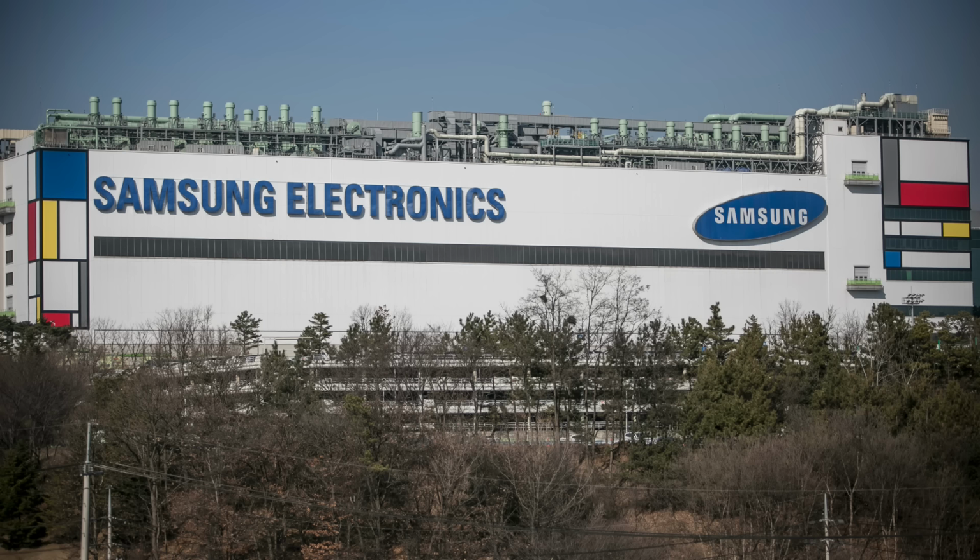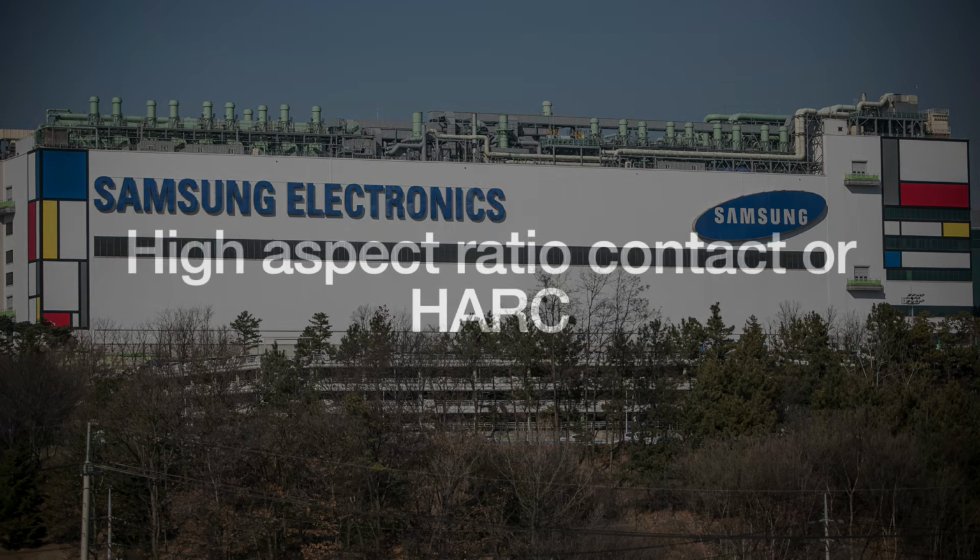But more layers bring more challenges, particularly with high aspect ratio contact, or HARC. Aspect ratio refers to the shaft's height to its width. We want to keep that high. A 128-layer NAND might have a shaft 100 nanometers wide and 6 micrometers deep, so around 60 to 1.